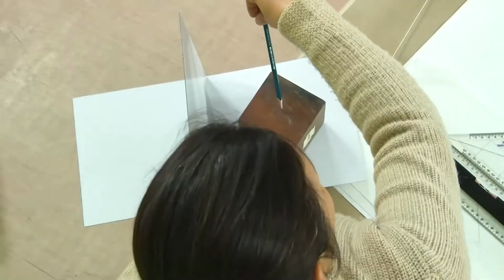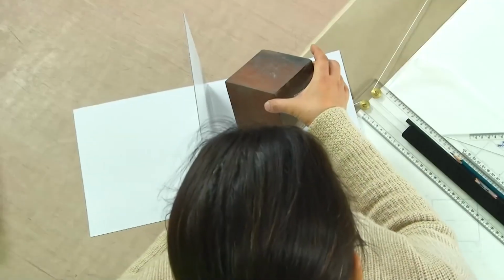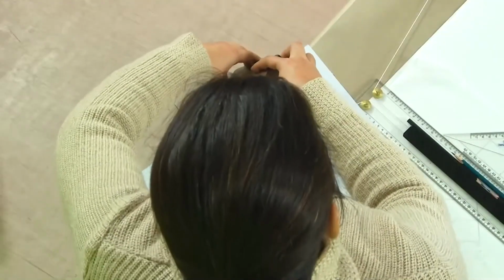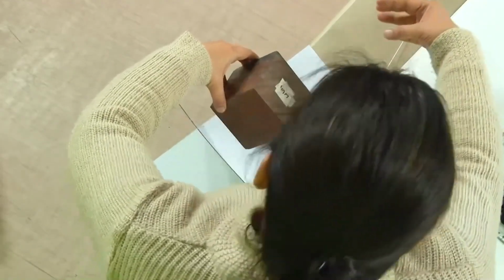So, what we have here is the axis still remains perpendicular to HP and parallel to VP. Now, inclining it such that the axis now makes a certain angle with HP. So, what we see is that the cube is inclined by one of its points like this. So, from the top, that is what I had asked you to do yesterday, when we see it from the top, we will actually be seeing three faces, and when you see it from the front, then also you are seeing these three faces being visible.